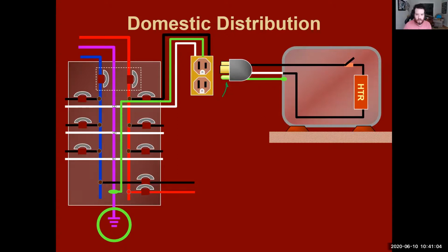All right, normal current flow is going to be going out of this black wire and coming back into this white one, going into the circuit, going into the white, coming out of the black, and it's all fine and dandy. If this black wire right here gets damaged and you have an electrified toaster, this grounding wire, it's a bare copper wire.